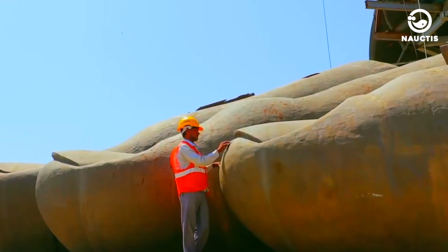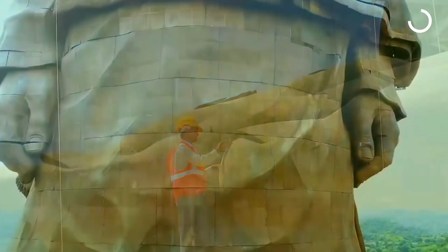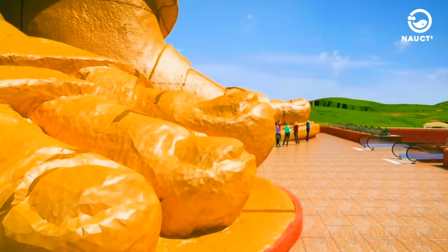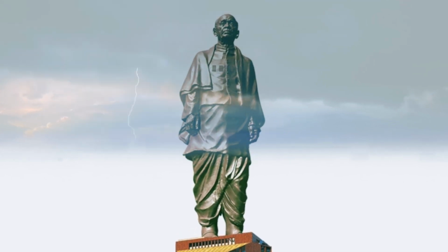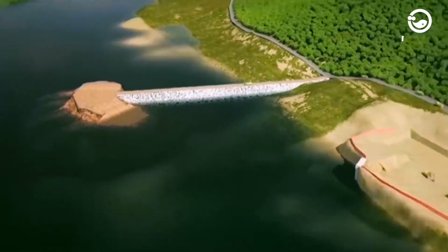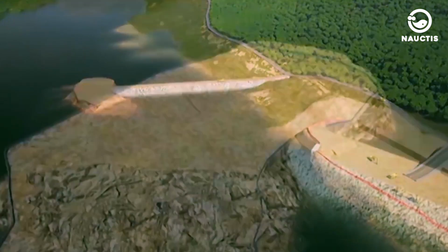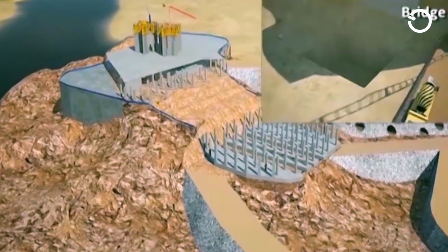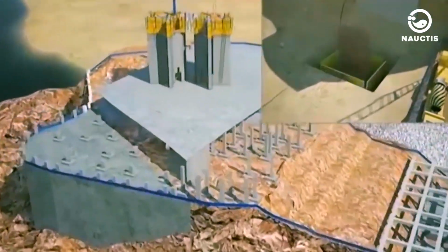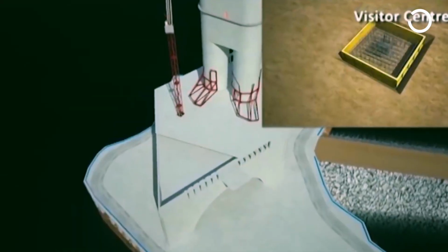For this purpose, the outer part of the structural grid frame was welded to the steel subframe. This subframe was connected to the clad panels to support the cladding system's weight and withstand earthquake and wind forces. Moreover, the clad panels were designed to have overlapping panels, allowing vertical and horizontal panel movement. Then the above process was repeated until the statue's completion.